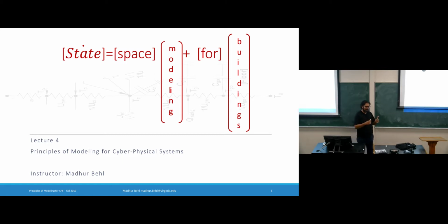Today, we will attempt to actually start modeling the system, right? So we've defined the CPS domain for the first module in this principles of modeling for CPS. But now we'll start with the modeling part. And while doing this modeling, I'll point out which principles generally apply to any CPS rather than just energy. And so we've spent quite a lot of time on looking at state space modeling examples, mostly from mechanical and electrical engineering. Today we will see what are the physics-based first principles that we use to model the thermal dynamics of this single zone to begin with.